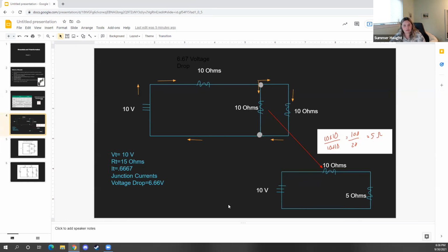What he did right here in the YouTube video was he drew something called an equivalent circuit. An equivalent circuit is basically what happens when you take your combination circuit and make just the parallel portion of it a series, so then you only are left with a series circuit. When they calculated the total resistance of 5 ohms here, now we only have 1 resistor, so we're not doing 2 anymore. So they rewrote this problem.